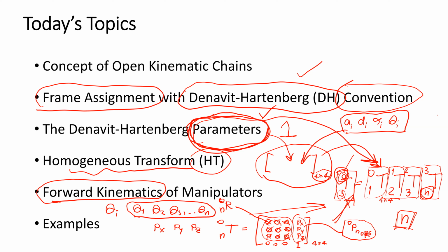And what is the orientation? And the orientation is represented by the rotational matrix. So the parameters of the link, we have 4 parameters for each link, but the link length and the link twist are the link parameters that are constant and never change.